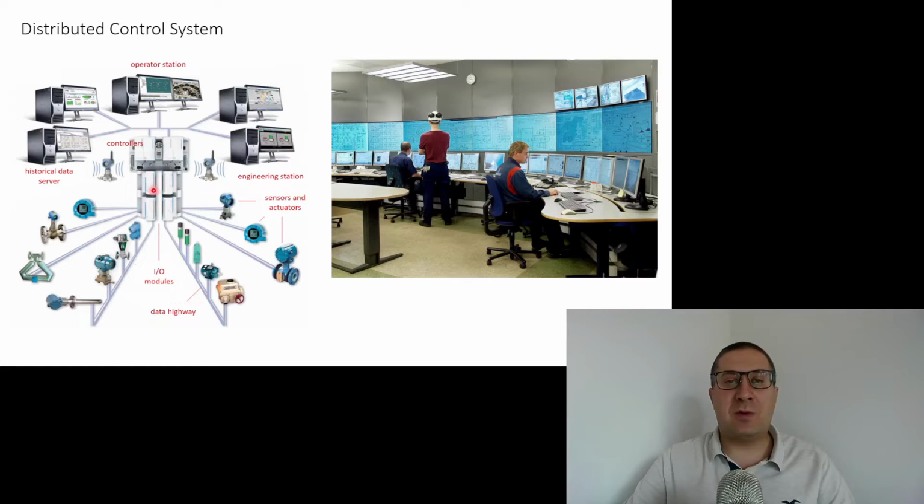We will also find a lot of sensors connected to those I/O modules that measure pressures, temperatures, flow, liquid levels, etc., etc. On the other hand, we also have actuators that affect our process, like valves, pumps, engines, etc. And they are also connected to input-output modules.